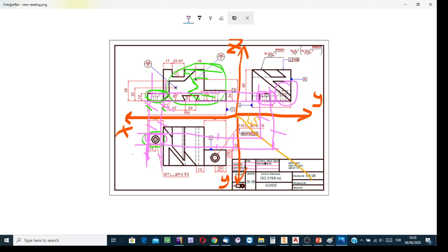At the region which is bounded by this and that, these are the transfer lines to transfer the delta z value from the front view to the left side view. And this and that, these are the transfer lines to transfer the delta y value from the top to the left. So you see these 4 transfer lines bound this region. It is the region to find the left side view. In this region, what do we have? Correspondingly, another rectangle.